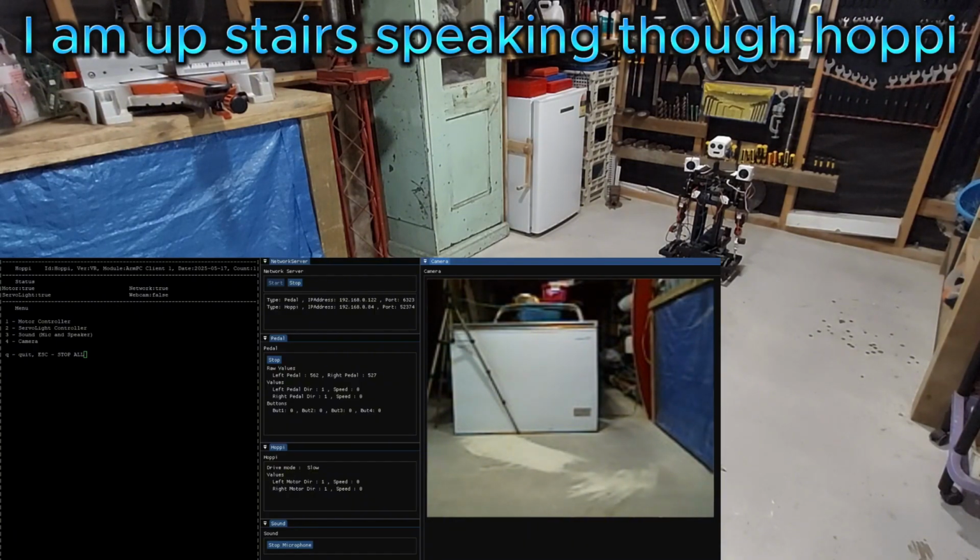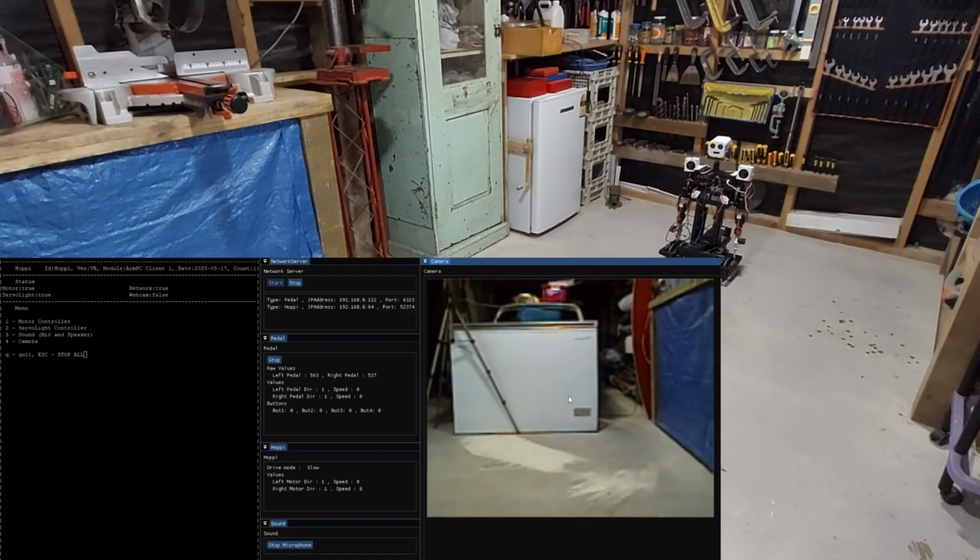You should be able to hear me now. I've got the camera stream over here. It's running at 176 by 144 and 10 frames a second. I can have it running at 320 by 240. But yesterday I put it up to 15 frames a second and I was getting a whole lot of delays, and I put it back down again and it was getting about a second latency. So now I've got it running at this speed and I'm getting almost no latency. In other words, I can have more high definition, but I prefer less latency.